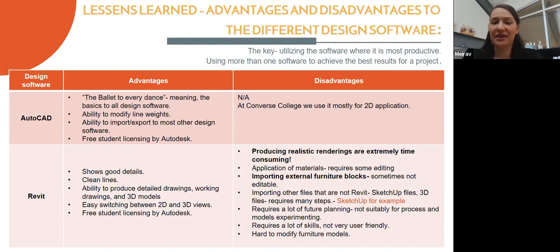So I was thinking, okay, there must be a way to convert a SketchUp model into Revit, right? It requires 3 steps: bringing it into SketchUp and editing it in SketchUp first, creating layers, bringing it into AutoCAD and putting it on a specific layer, and re-bringing that into Revit. And then what? Materials are not editable.